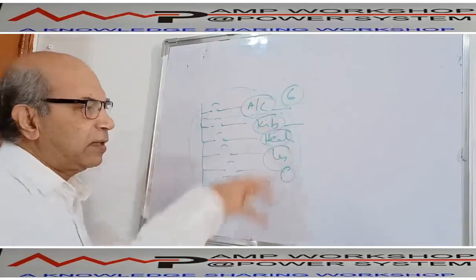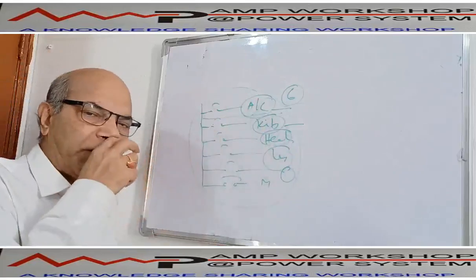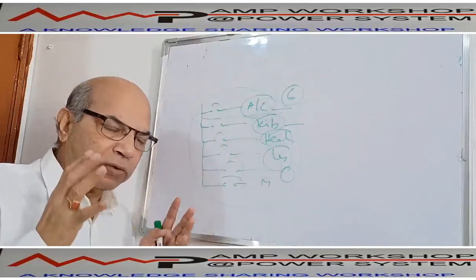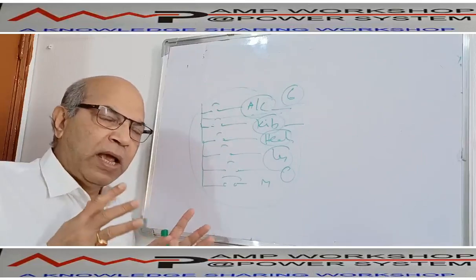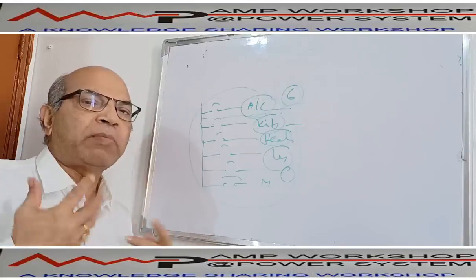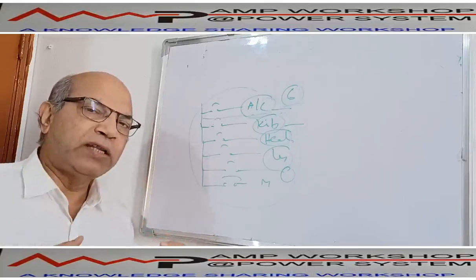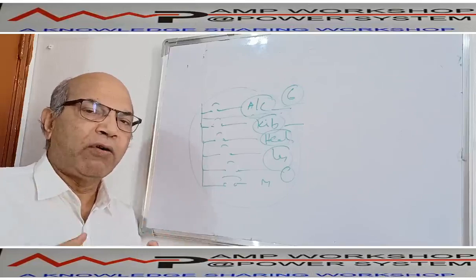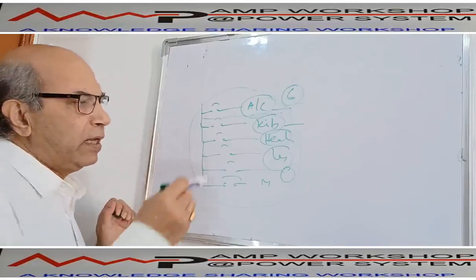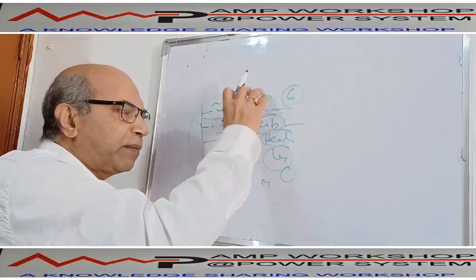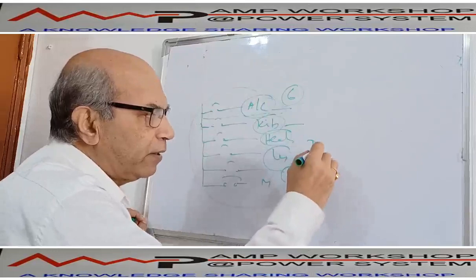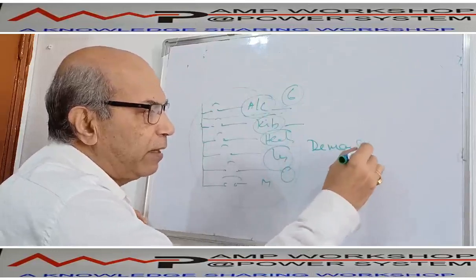These are the various subsystems. For each subsystem, we have to find out, of this AC subsystem, whatever the total kilowatt connected to the system, or at a particular instant, what is the maximum number it can run, or maximum kilowatt. When we want to decide this factor, we define it as the demand factor. Demand factor is defined as the maximum demand of this subsystem, or maximum running load on that subsystem.